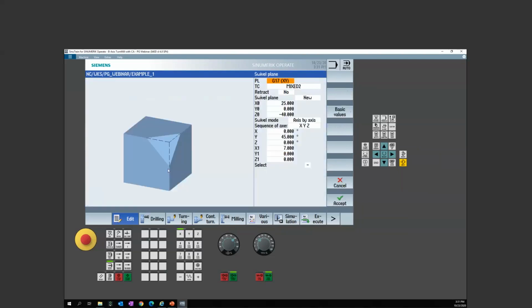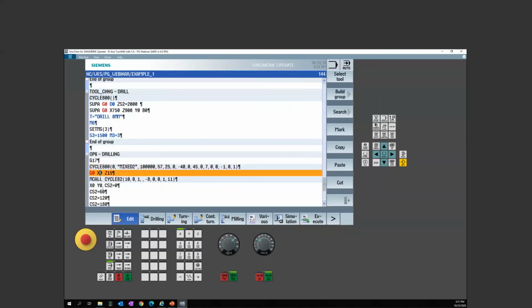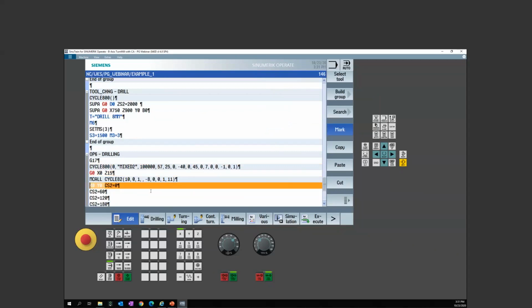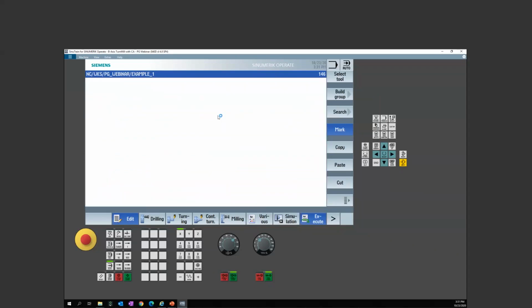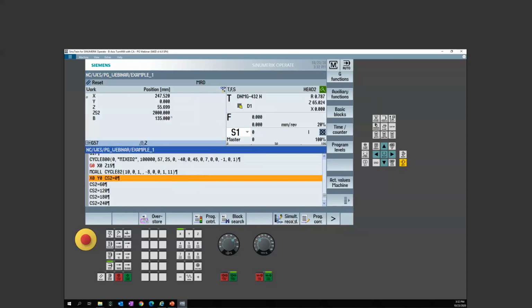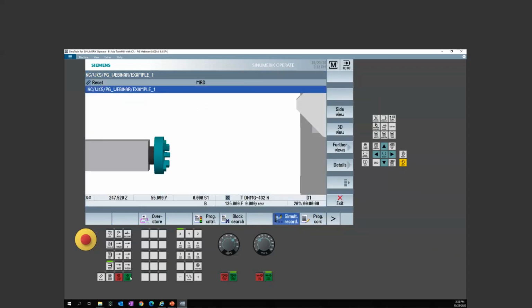Now in this case, I actually had 2 different shifts because I wanted to get all the way back on that chamfer. So I shifted it up and over to the start of the chamfer, and then I rotated the coordinate system 45 degrees, and then I slid up that new plane by 7 millimeters. So that was why I was able to go to 0, 0 for my drilling. And then you notice, since everything was spinning around the center line of that part, I then just added some C commands to drill all my holes. So my final piece, we'll take a final look at it, and let's run her.